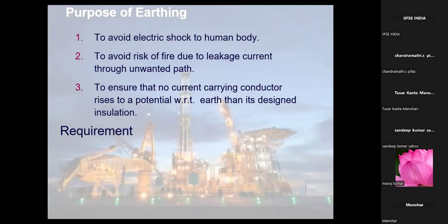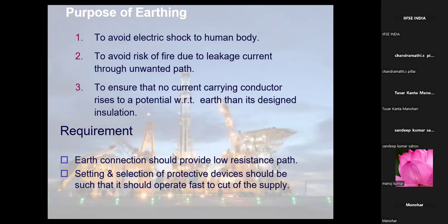Now, for a good earthing, what are the requirements? The earth connection should provide a low resistance path. The setting up and selection of the protective device should be such that it operates fast and cuts off the supply. Now, I think most of you are working now.